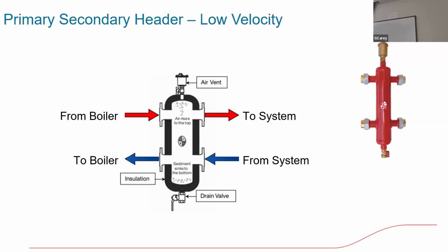So as I'm taking the heated water out of the boiler plant, and before I get out to the system pumping, I'll pass through this low loss header, and because of the low velocity area, I will collect any of the air bubbles that come out of solution from the heated water from the boilers, and I'll vent them out the high capacity vent at the top here. So it's just another method.